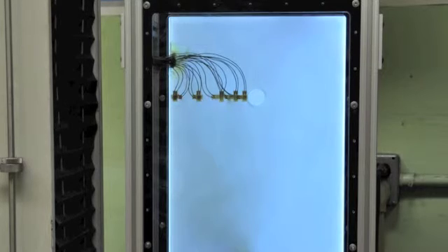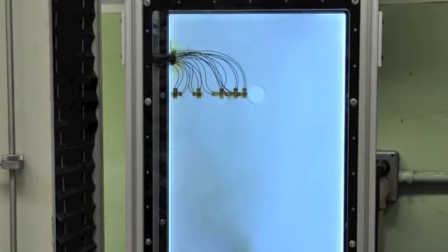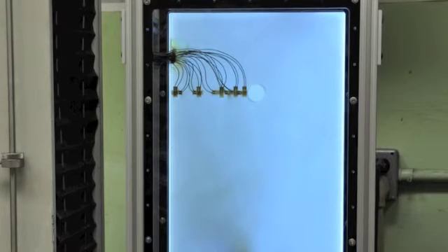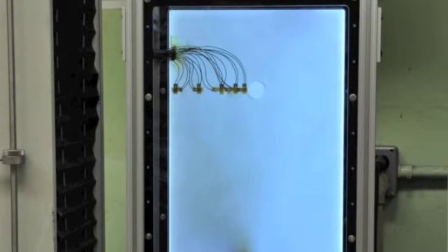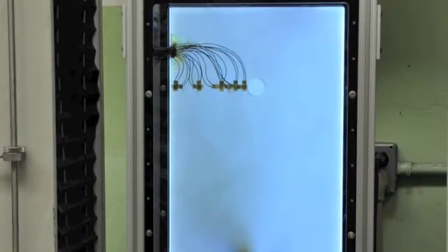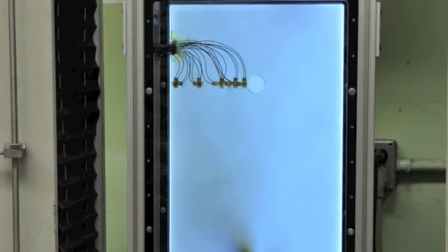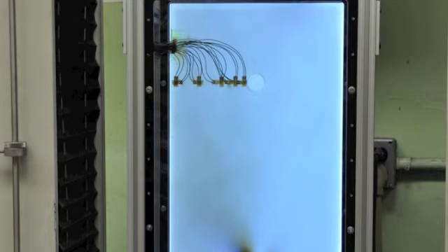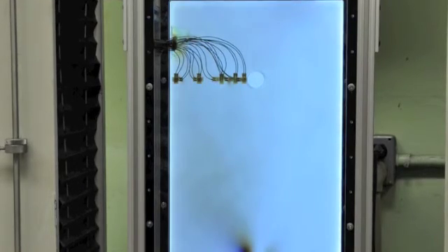Here I'm going to talk a little bit about photoelasticity. So basically, when a load is applied on a piece of isotropic material, which is polycarbonate in our case, the material would lose isotropy in one direction, resulting in birefringence, meaning that the deformed area will exhibit two different refractive indices. This will result in a relative phase retardation between the two waves, and that explains the color change we observe in this lab.